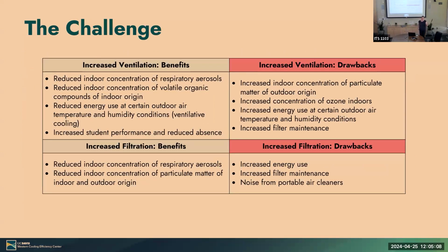So the challenge is that ventilation has benefits and drawbacks, and that changes depending on what's happening. As we increase ventilation, we bring in more outside air, we reduce the indoor concentration of respiratory aerosols that we're breathing all the time. We reduce the concentration of chemicals, volatile organic compounds, and off gas from furniture. We reduce energy use when the outside air is at a nice temperature, essentially. And increased ventilation is associated with reduced absence rates in schools.